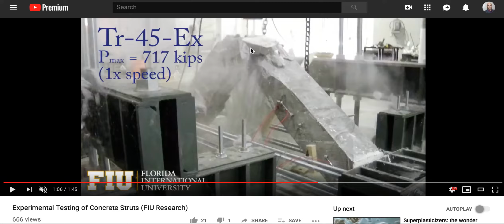That the forces resolve themselves each time at the top of this member, not at the base. Equally they pushed back from pushing in, and I'm going to stick with that. And the cross section up here was obviously not strong enough. We just saw a shear break happen a moment ago, and my guess is that load coming down created a shear also inside this, but there was nothing to split down, so it was able to defeat itself up there in this nodal area.